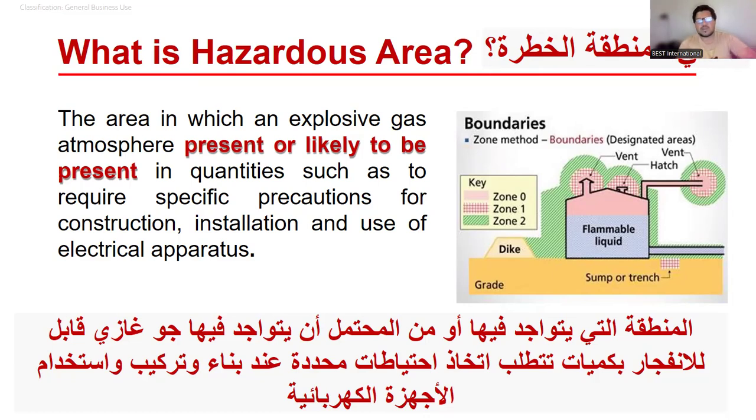How do we close the valves? How do we make sure of drainage of all hazardous materials? How do we make sure of proper locks and tags? How do we purge and water wash to make sure the LEL is 0% if you want to go for hot work? And bear in mind, for hot work in a confined space, LEL has to be 0% at the start, during, and after. Make sure you maintain LEL at 0%. Otherwise, no hot work.